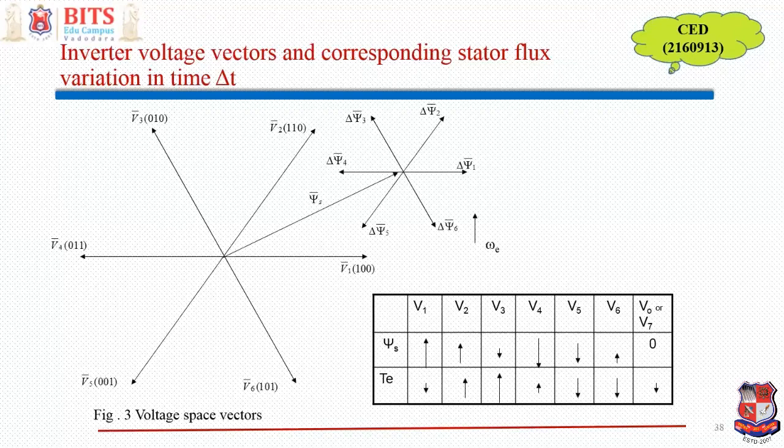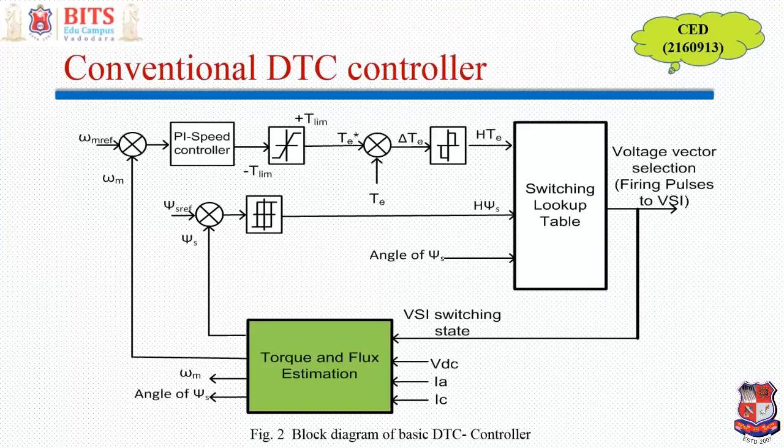So that is the fundamental of a direct torque control. Now look at the operation of direct torque control. So what do you do over here? I have a speed reference. I measure the actual speed and give it over here.